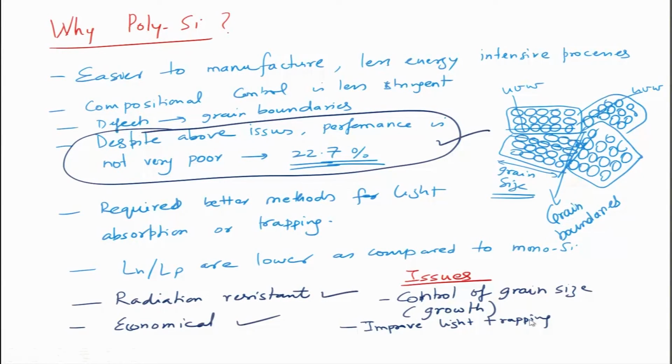Remember, in monocrystalline silicon, the top surface is all 100 plane, and when you texture it, everything becomes 111. So you have these facets of 111 planes. So in single crystals it's easy.